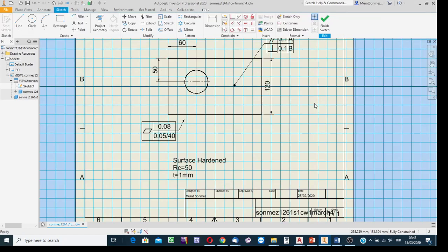After the click, you find the projection and all the things on the page in sketch mode. To be able to locate the chain line at a certain distance away and in a certain length, this is a must. Apply the project geometry process. Click on this, and then using the windowing method, have the projection of the view on which we are going to show the necessary chain line. To be able to select all the things on the view, use the windowing method.